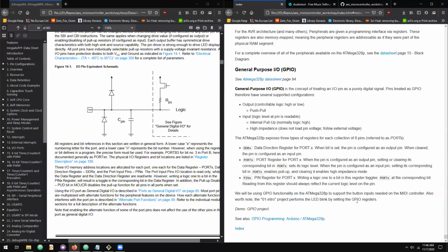And we'll need this specifically for if we want to set the LED, then we'll need to configure the LED pin as an output and set its logic level. But at the same time, we're also looking to support buttons. So if we want to be able to read our button state, we need to configure those button pins as inputs. And when we get to the actual hardware layout on this project, I'll give you guys a schematic for how to hook up the buttons to the correct pins on the Arduino.